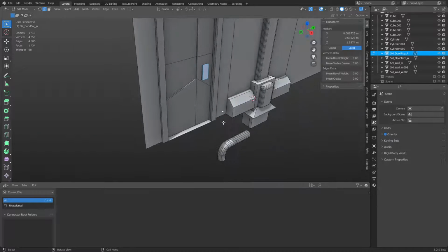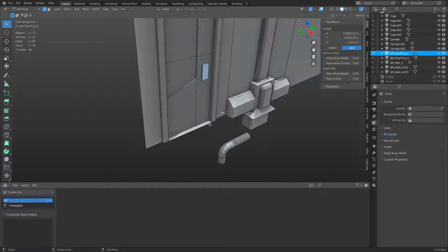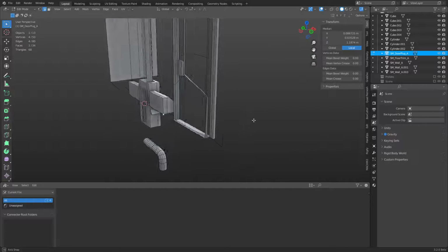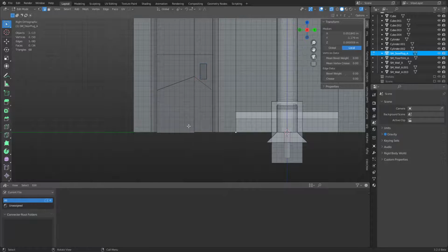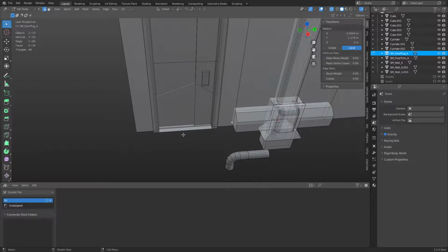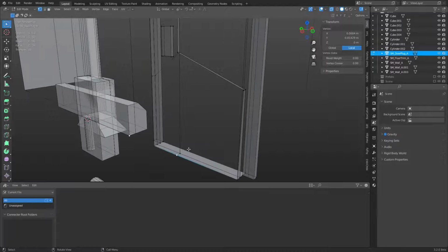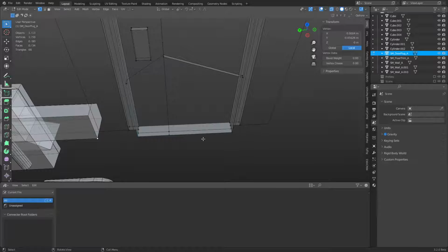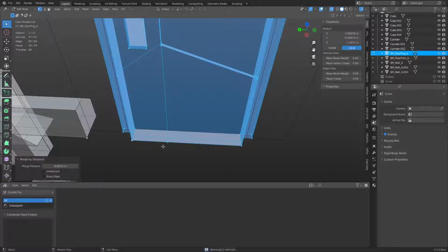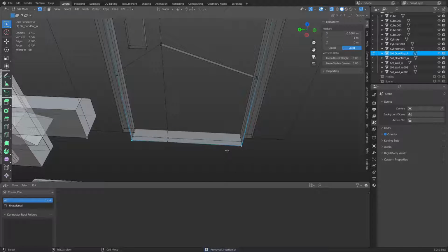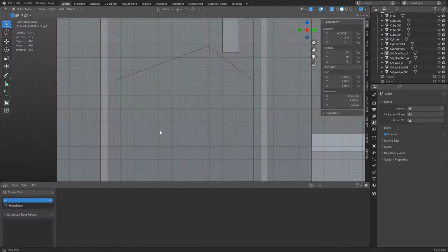And so the door plug itself, if this was a non-enterable door, like you're never going to use it, you can get away with this where you just, more or less, I'm going to grab this vertex. Well, let's select everything and merge it by distance real quick. We're going to take these two and place our origin point at the center. We can get away with this.